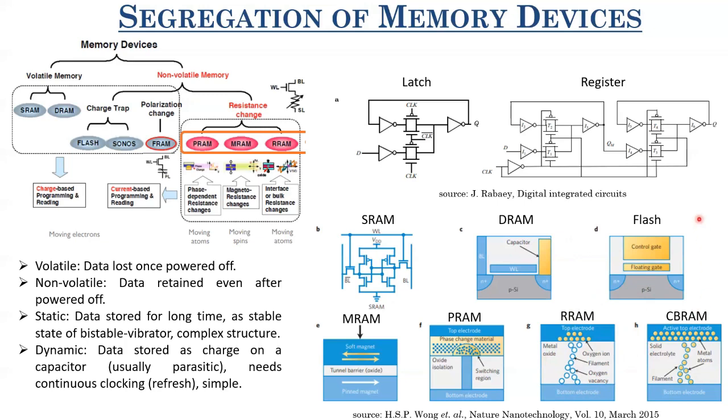So let us now discuss the problems with all the memories. With resistors or latches, the number of transistors is large, so area is large. Speed is high, but area is also high. SRAMs: area is large, static power leakage is large. Also, noise margins reduce significantly when we are scaling the devices. That is something that we'll discuss when we talk about SRAM. There's a special module for it, don't worry.